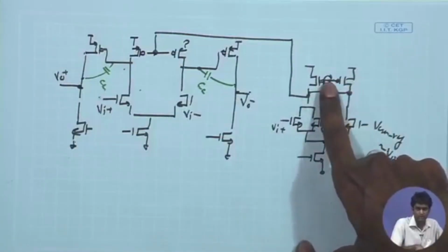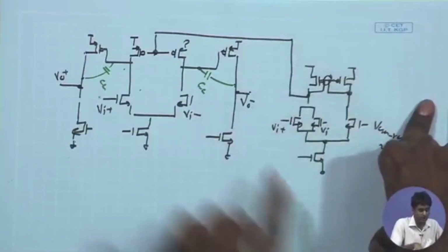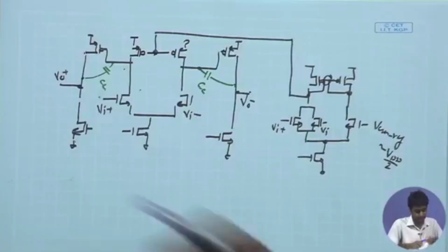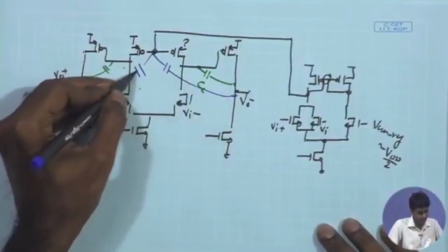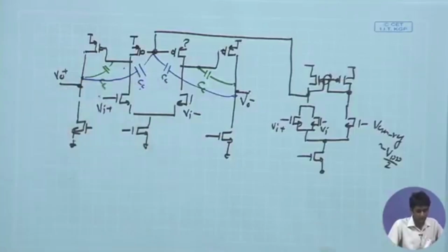If I stick to a current mirror load, that means this stage is going to have a large gain of GmRo, and then put a cap between these 2 points for the compensation of the common mode loop. This is what is going to be the pros and cons, whether it is a good scheme, whether it is going to give us appropriate compensation for the overall loop response for the common mode.